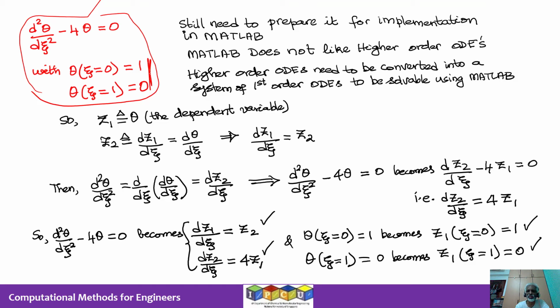Matlab does not like higher order ODEs. It does not like terms like this. It only accepts ordinary differential equations that are first order. So whenever we have a problem that involves second derivative, third derivative, etc., we have to convert that ODE into a system of first order ordinary differential equations. Matlab only accepts systems of first order ordinary differential equations. So this is a key point: higher order ODEs need to be converted to a system of first order ODEs.